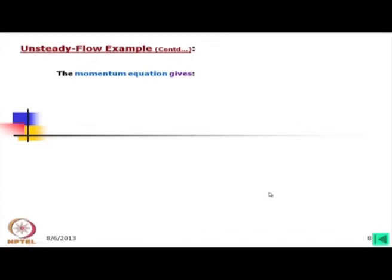Now, the momentum equation gives P1A minus P2A is equal to rho q v minus rho q v minus d by dt rho A L v. A into L is the volume, v is the velocity and rho is the density, that is the mass. So, rate of change of mass minus the mass in.